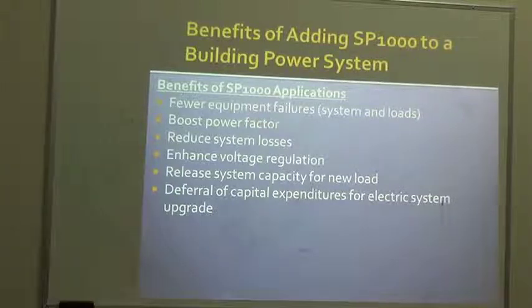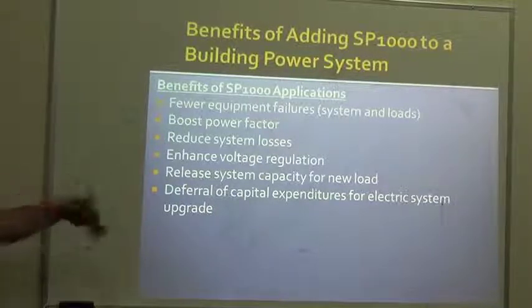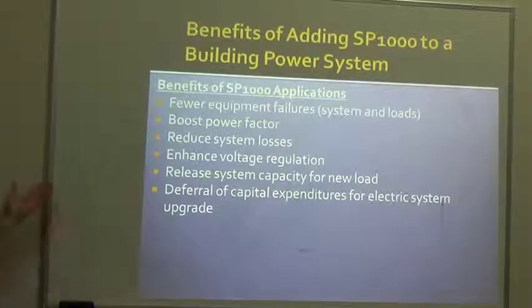I'm flying into the airports and I'm seeing these buildings with solar panels everywhere on top of them. That is affecting their reactive power, because this is another one of those power supplies. This is a nonlinear load. It's just doing things a little bit differently than some of the others. We're converting AC to DC and DC to AC and all that good stuff. Same thing here with inverters and drives and everything else. It's the same action. The switching of the transistors is what's creating all this harmonic power that's hurting these buildings and costing us money. Does that make sense?